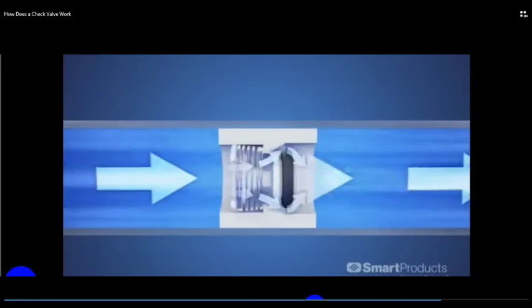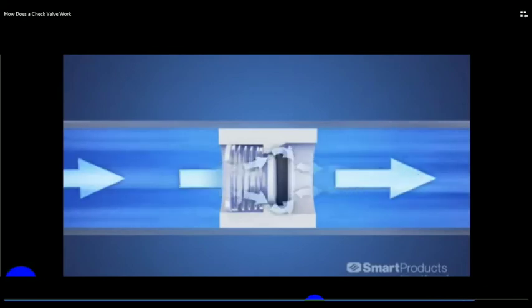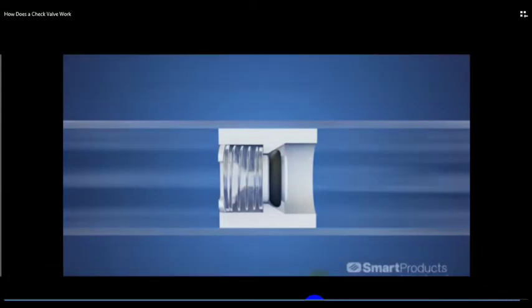Now pressure decreases, and the components begin to move back. Reseal pressure is around 20% lower than the opening pressure. Finally, the spring force compresses the O-ring enough to hold it in place. The valve reseals and resets, ready to repeat the process.